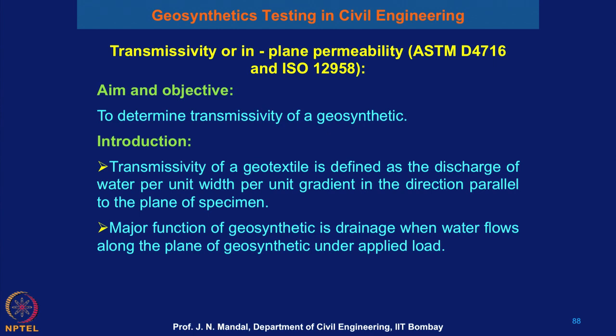The major function of the geosynthetics here is drainage, when the water flows along the plane of the geosynthetic material. So, remember the difference between the two: one is filtration, another is drainage. In the case of permittivity, it is filtration, and in the case of transmittivity, it is drainage. That means the water flows along the plane of the geosynthetic material.